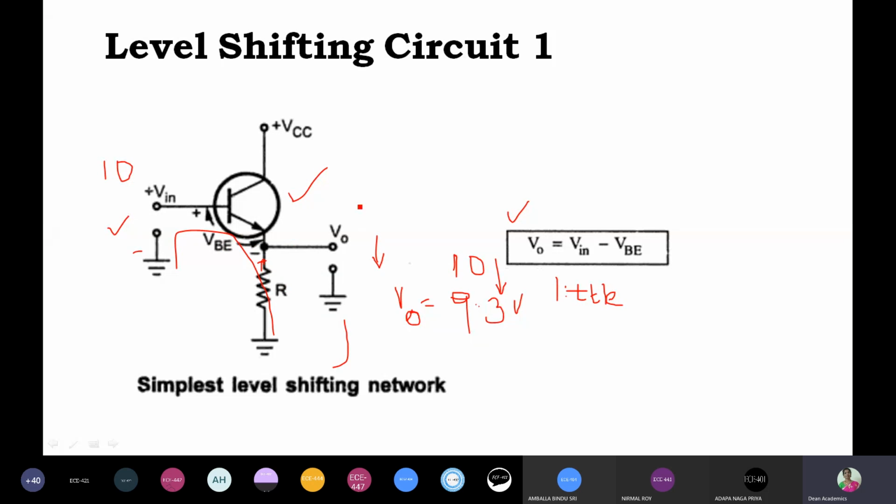That means the AC voltage gain or differential gain should be the same, but we are trying to eliminate this DC component, the DC output voltage. The DC output voltage we are able to reduce only to some extent. So now we modify this circuit.